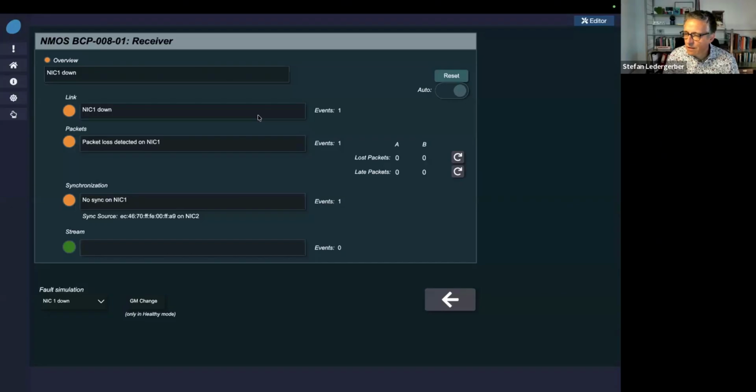In this case, you see that every traffic light has an information message field. And we don't tell the manufacturers what to put in there. We just give them examples and encourage them to put in meaningful messages. On top of that, we have a counter. Those counters increase with every incident you had, and they normally stay and give you a little history indication. Obviously it's still down to the control systems to log the messages, but this is a little indication in the edge device right away.